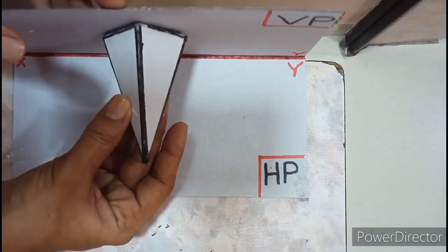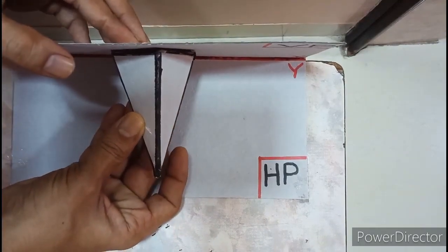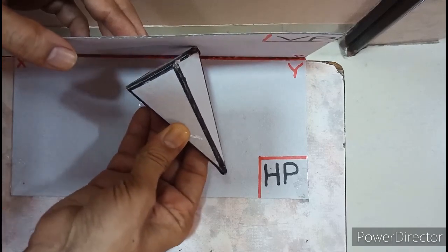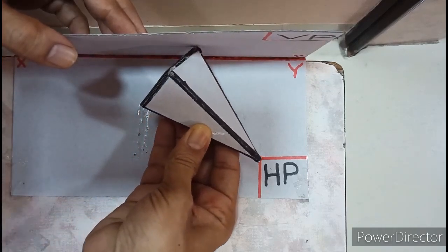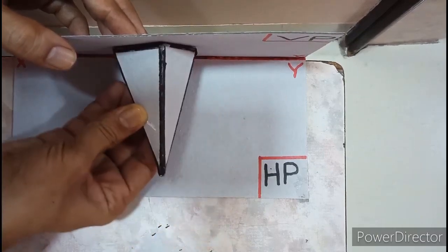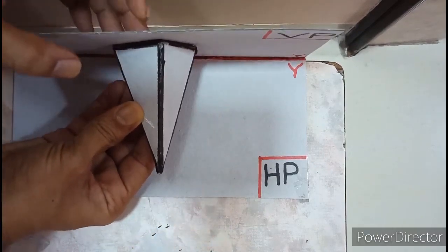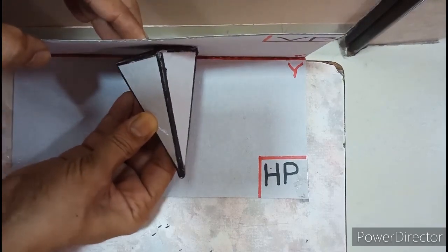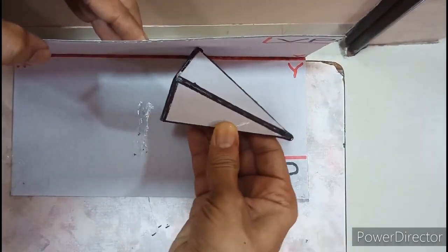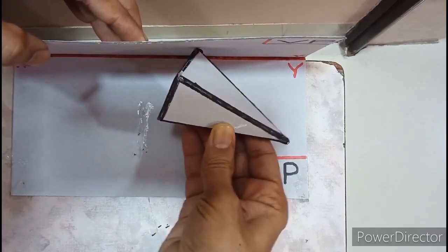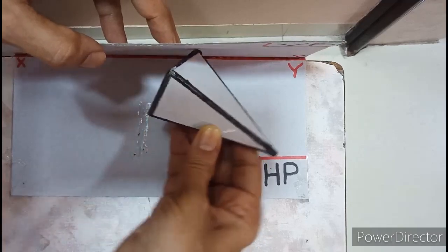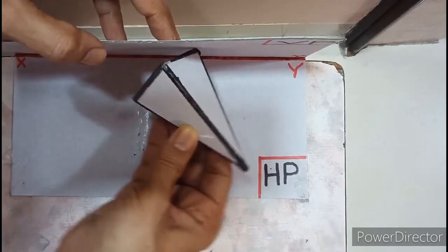What you have to do is, if you look in the top view perfectly, the entire base was resting in the first stage. Now tilt, only the corner should rest, and the apex distance should be 75 in front. If you carefully observe, from the top view the outer shape of the triangle remains the same, it doesn't change. Only the orientation of the triangle has changed. So you have to tilt like this until the apex is 75 in front, and that you can see only from the top view.